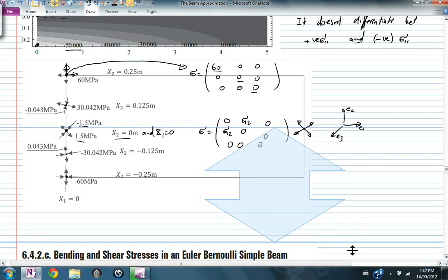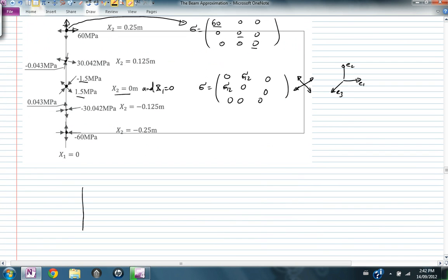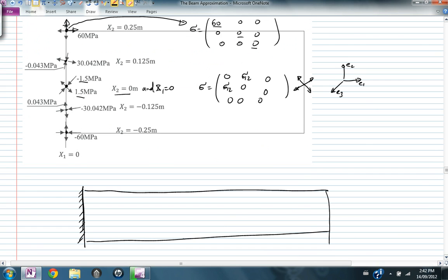Now, just to give you a bit of why I would want to do this, a bit of the application of something like this. Whenever you design a cantilever beam, and let's say I'm going to make it out of concrete, I care about the direction of the principal stresses. So at the top here, the principal stresses are in the tension direction. So I'm pulling the concrete in this direction. Because I'm pulling the concrete in this direction, usually you find that in a cantilever beam, they put steel bars at the top to take this tension. In the bottom, there's more compression, so I don't really put a lot of bars closer to the bottom fiber of that beam. I might put some just to make it strong, but I don't really need them to take any kind of tension.